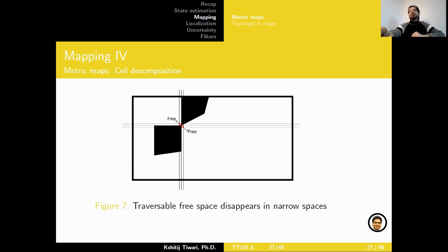And I've only covered very basic cell decomposition methods, so exact and fixed cell decomposition, but there are also extensions like adaptive decomposition, which means when something like this happens, or around the obstacle boundary, you use a much finer resolution grid, but other times you use a much coarser resolution grid. So it's like a multi-resolution grid, and that takes care of not having these kinds of problems, etc.